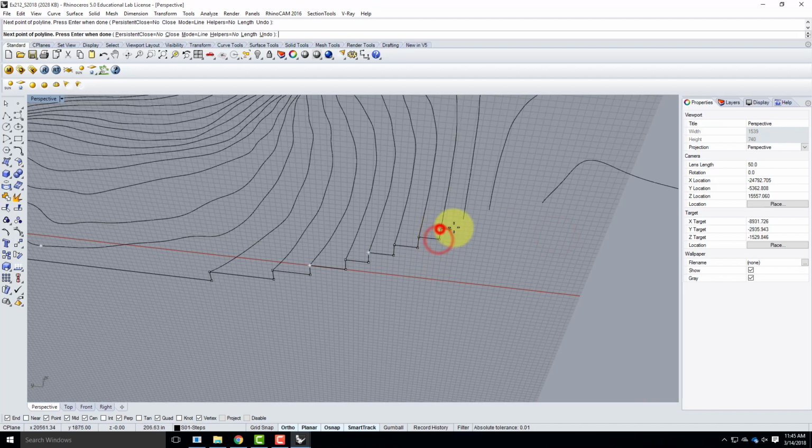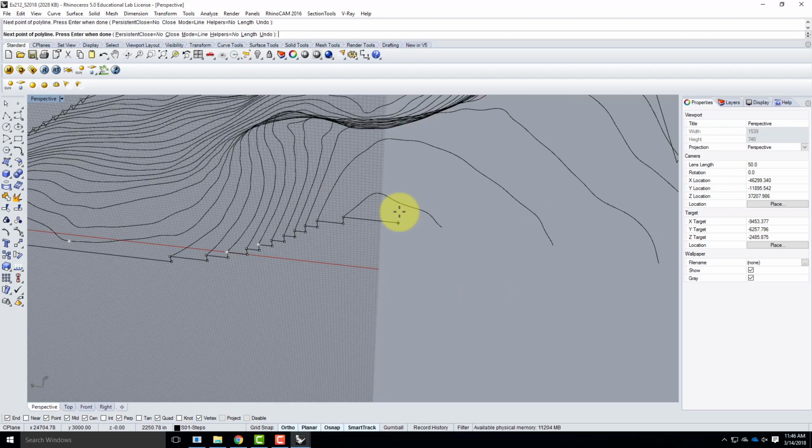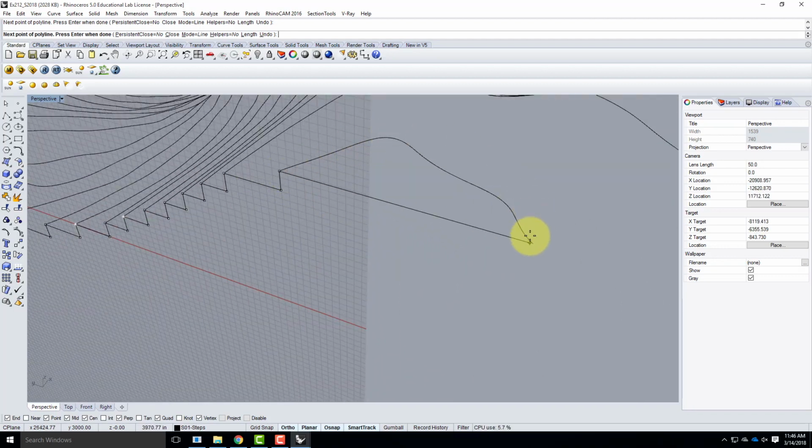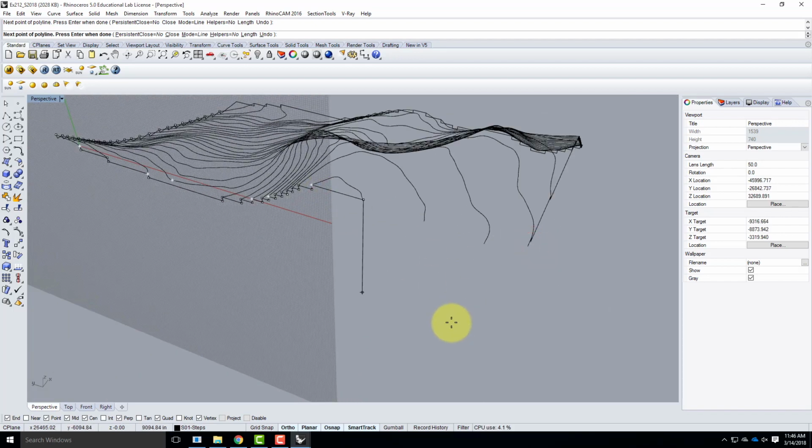That's if there's one that's just lower, right? That's if there's two parallel and you're going down. So I'm about to get to one where I'm going up. So I've just gotten to this point. And at this point, this contour here comes around and connects to that point. But it's at the top of the hill, not at the bottom of the hill. So since it's at the top of the hill, and I've already made my step up to that contour, I just go straight across there. So if it's at the bottom of the hill, you're going down your contour amount. If it's at the top of the hill, you can go straight across.